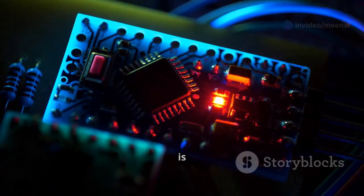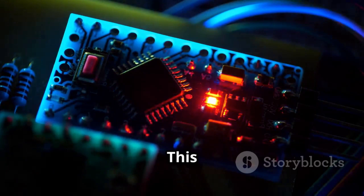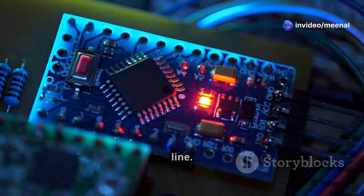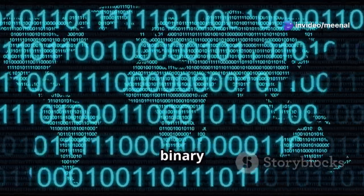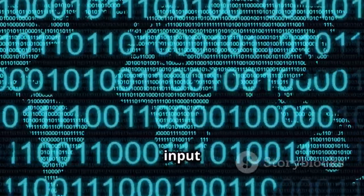The output, however, is serial, with data exiting the register 1 bit at a time. This serial output is ideal for scenarios where data needs to be transmitted over a single line. Imagine loading the binary number 1010 into the register. This binary number is loaded in parallel, meaning all bits are input at the same time.